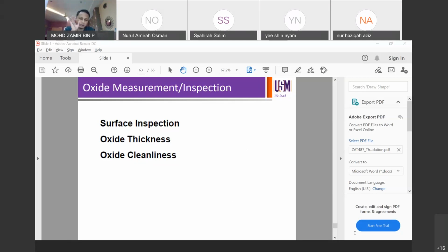Then the wafer is gonna be on hold, waiting for you as process engineers to come and troubleshoot, find the root cause. Then only you can release the wafers for the next processing. Okay, so it's called process spec. On the process spec dalam SPC chart tu, there'll be target 5.0 nanometer. There'll be upper control limit 5.3, lower control limit 4.7, assuming that the plus minus is 0.3.